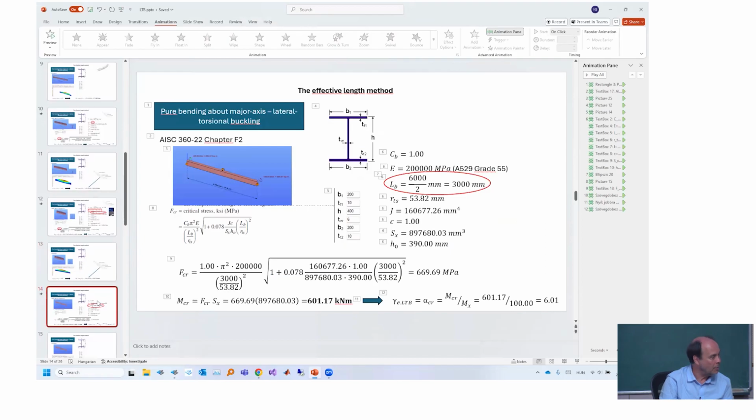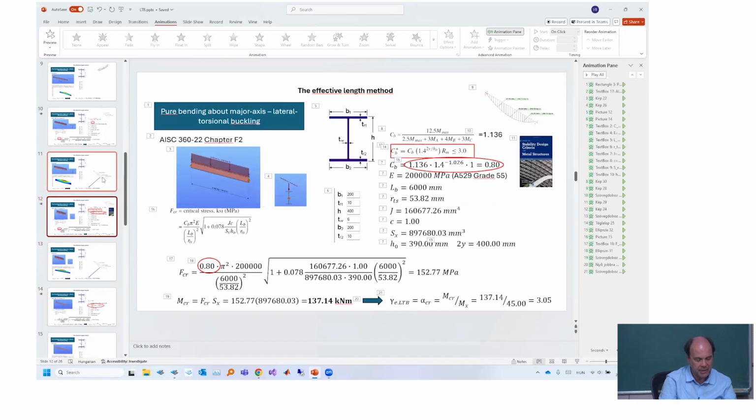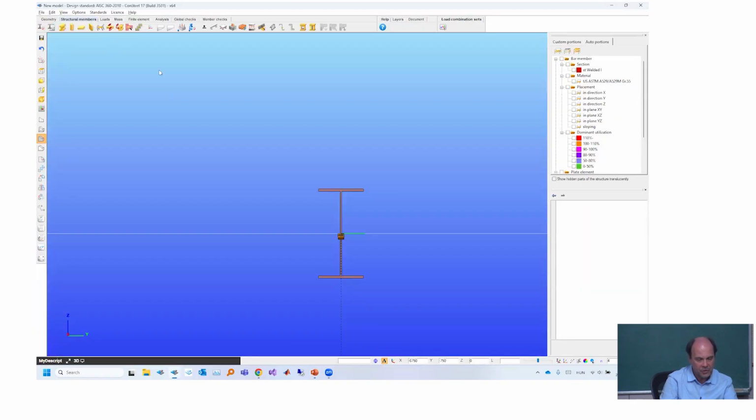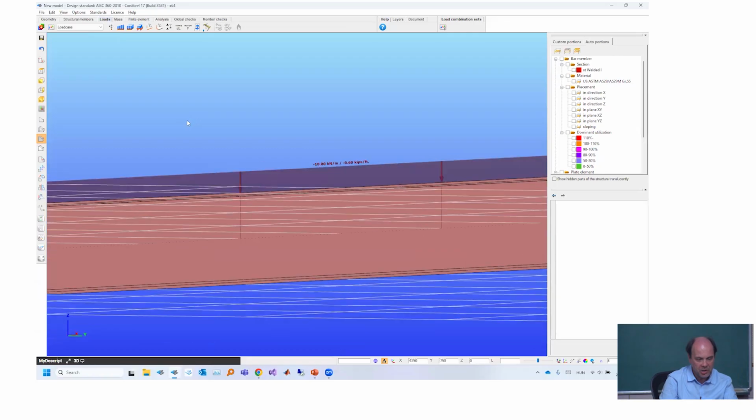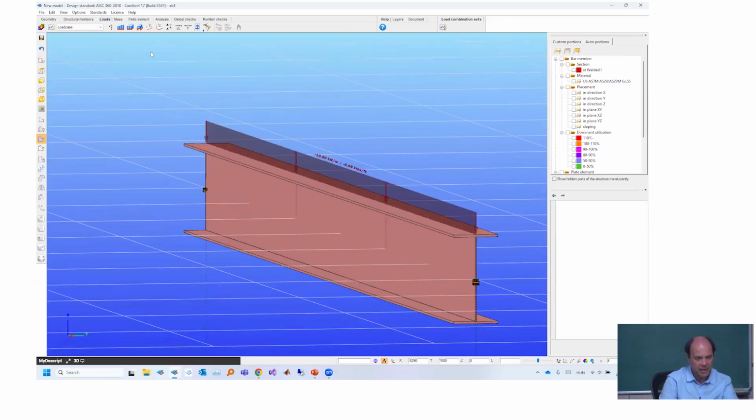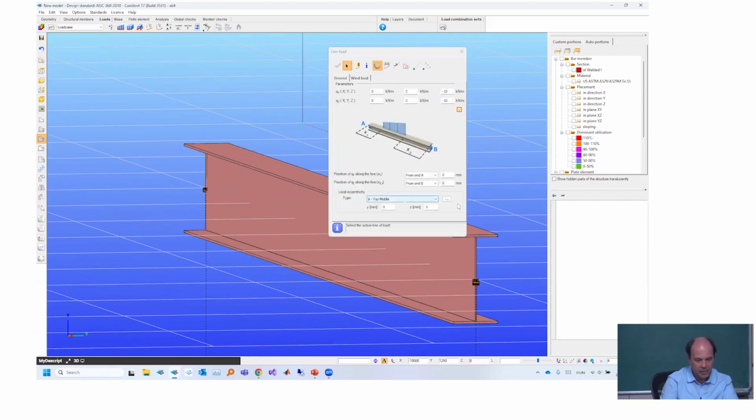There's also an option where you can put that load above the flange if you want, right? Yes, we can put in addition eccentricity. So we can also not just use this point as we wanted, but I delete it because it's a bit more visible when I define. So I can say top middle, and then in addition, I can specify additional shifts by offsets. So I can say that it's 200 millimeter above the top flange. So in that case, I said an addition 200, and it will be even higher. I could move it also to left and right.